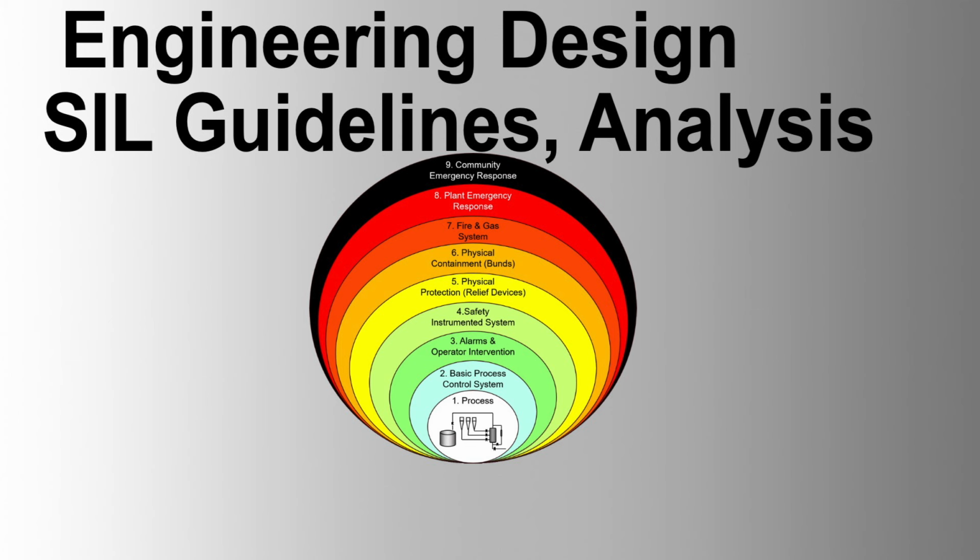Construct fault trees using appropriate failure logic, starting from the top event and identifying all basic events that could lead to this top event. Include primary, common cause, and systematic failures. 4. Qualitative review of the fault tree structure. Review the fault tree with process and instrumentation designers, operations, and risk assessment teams to ensure all significant pathways to failure are captured.